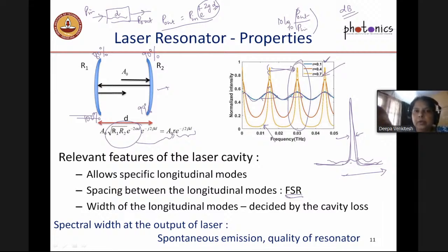And that Neper unit will be in the exponent, so it will be dimensionless. So when you say it is in Neper per meter, you should understand that it is the gain per length, which is in the exponent. If I say it is dB, it means that it is simply the ratio of output power to input power. So that was one question.